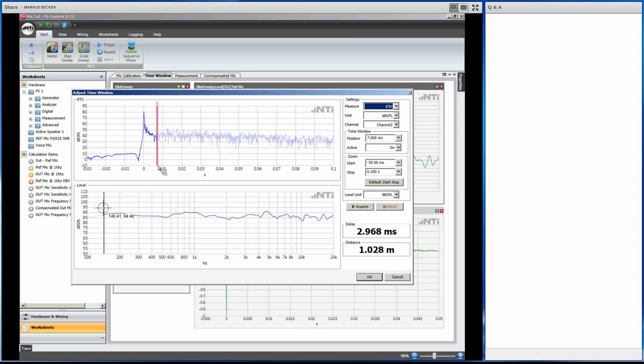Maybe you have noticed here there is a black vertical line which has appeared, and that is an artifact that is a consequence of my time windowing. Because I'm restricted to this limited time here from the direct sound to this start of this time window, I cannot represent the very low frequencies in my frequency response. I can show you the impact a little bit more if I move that further forward here, further shorten this time, and then you see this line comes further here to the right hand side, which means that this part here to the left, the shaded part of the curve, it's just an estimate.